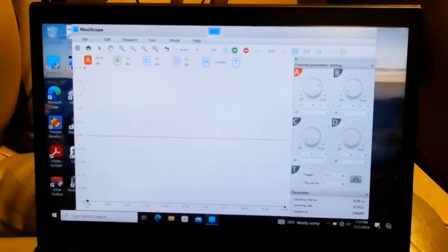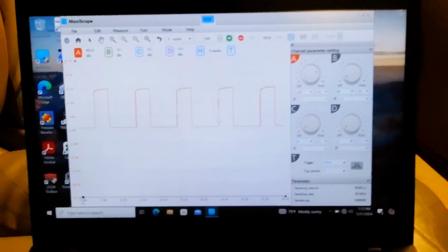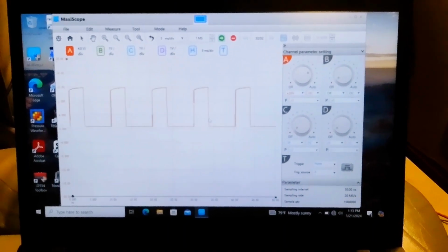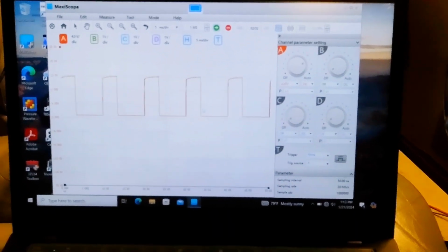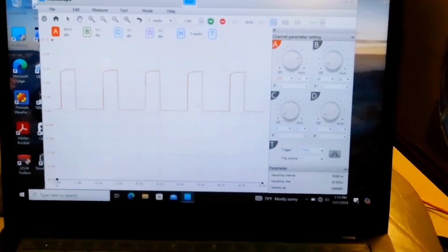Green and black. I'm going to back probe that. This will be your small diameter wire. You can see we have a good pulsed signal here. See if I can get my probe to stay in. Okay. So now on the HVAC control module, I'm going to vary the speed command. There you go.